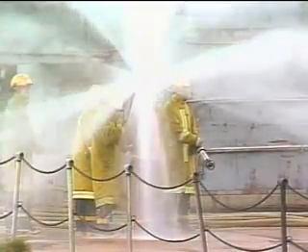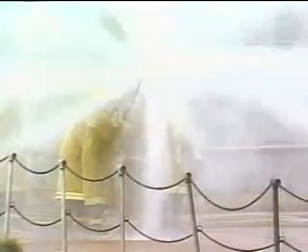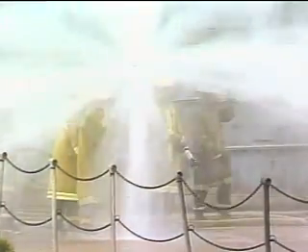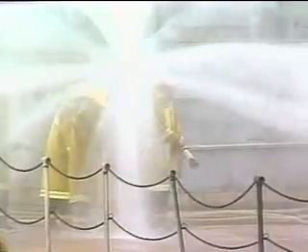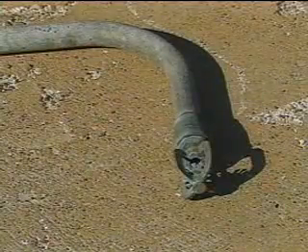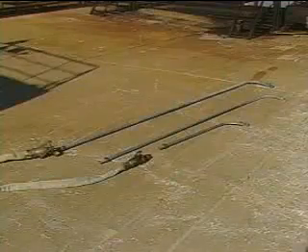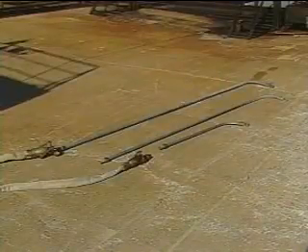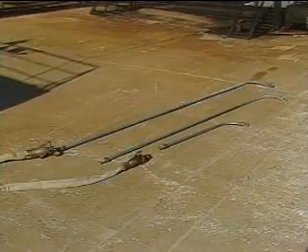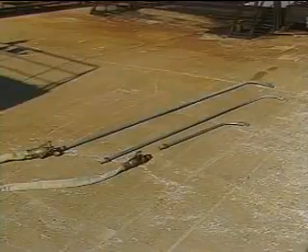Applicators, which spray only in a flat fog pattern, are usually available on board ship. They can be quite effective as support devices. There are 3 sizes of applicators. The 4-foot and 10-foot applicators are used with 1.5-inch nozzles. The 12-foot applicator is used with the 2.5-inch nozzle. The 4-foot applicator is used on interior fires. The 10 and 12-foot applicators are used on weather decks.